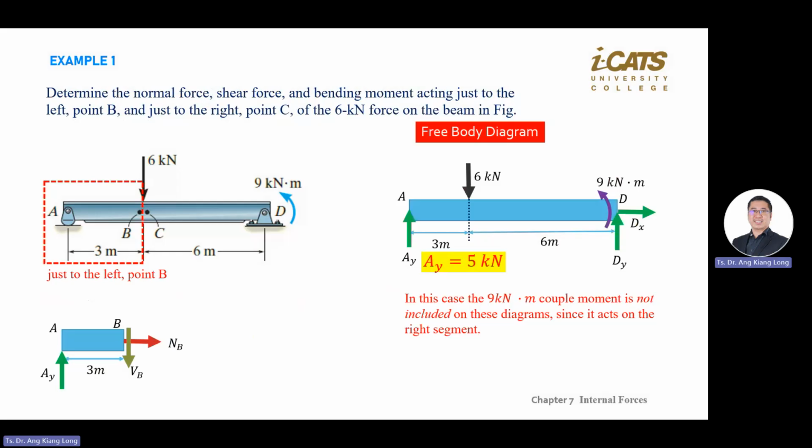Why is this side going down? Because we always use a positive shear diagram, positive shear. So VB goes down because it's on the left. Then the moment, like this one. Moment and V go away. You're still following the positive diagram that I showed you just now. We just assume the direction like this. Why? Because all the numbers that we determine are positive values, which means what we assumed so far is correct.